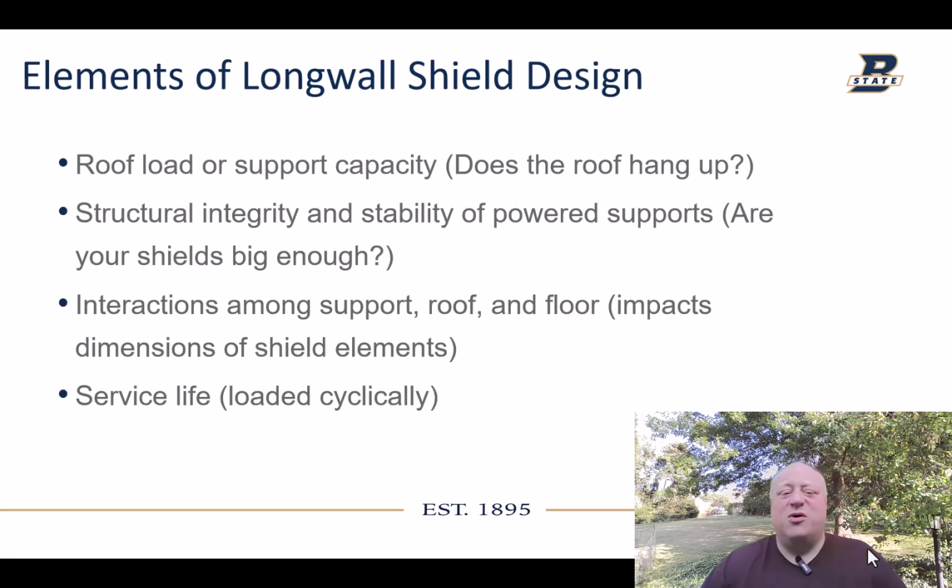So, elements of longwall shield design. First is the roof load or support capacity. You want to design the capacity of the shield, and to do that, the basic question you're going to ask yourself is, does the roof hang up? And you'll see what I mean here in a minute. Two is the structural integrity and the stability of the powered supports. Are your shields big enough? And are they designed in such a way that they can't topple over, right?